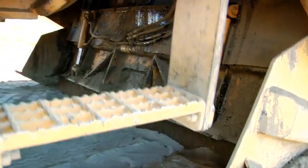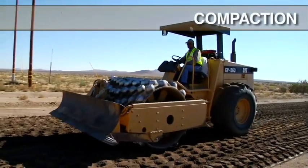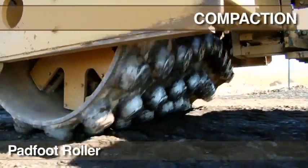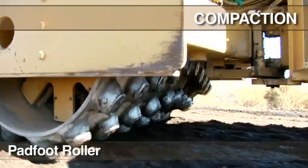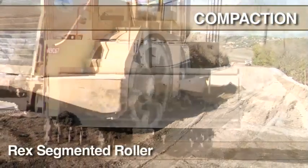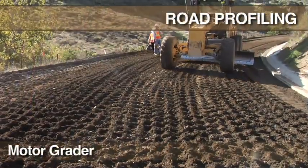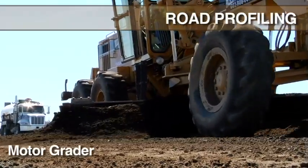Within 30 minutes of the emulsion injection, the compaction process should begin. A pad foot roller is needed to provide the deep lift compaction. The pad foot roller will continue to roll until it reaches its maximum density and has walked out of the material. On roads with reclaimed depths greater than 8 inches, a Rex segmented roller is recommended. A motor grader will then be used to remove the pad foot marks and provide the desired roadway profile.